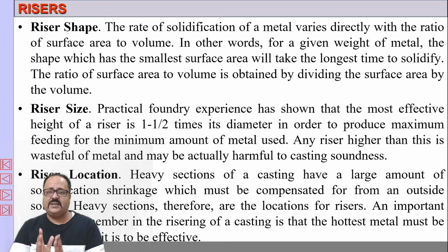That decides the solidification time. Obviously, if it is cylindrical, the surface area will be lowest, and if the surface area is lowest, the volume by surface area ratio will be highest, and therefore normally the riser shape is cylindrical.